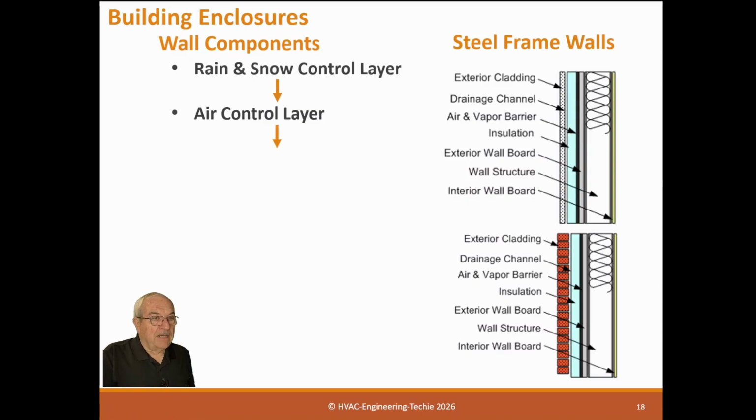Many, many times I've asked an architect, explain to me your theory on a vapor barrier. Where are they? And you'll find out there's no vapor barrier at all. Because the easy way out, unless you're building down south where it's really humid, but if you're in a mid-climate, Midwest, West, you can get away with no vapor barrier at all. What it is, the water comes into the wall structure, penetrates it, and then as soon as it gets dry outside, it goes back out. And they can go in and out.